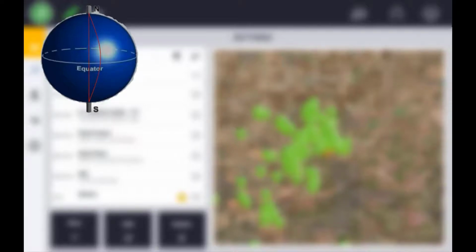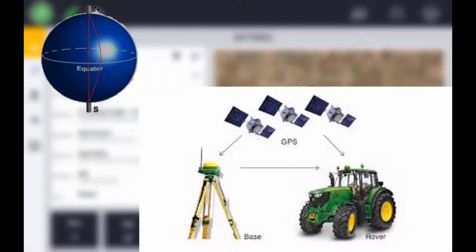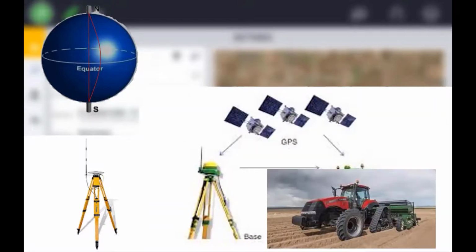Although the line generation will now follow that of the John Deere system, for these guidance lines we need to allow for difference in the initial position created. This difference in position is due to the John Deere system using its own correction source, which could be different to that of the Trimble system you are using.